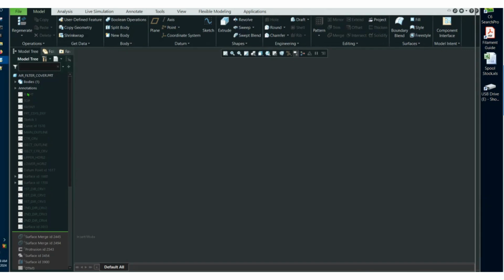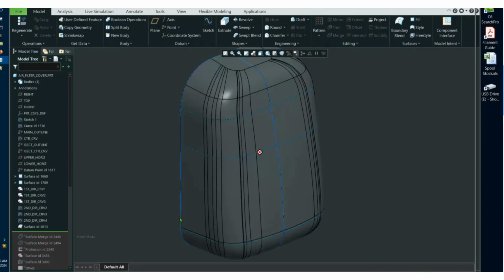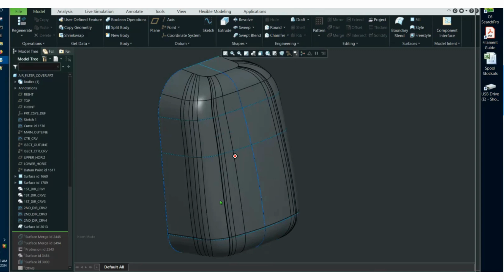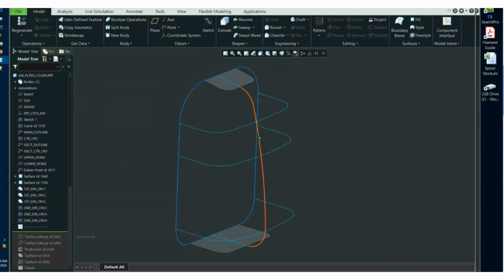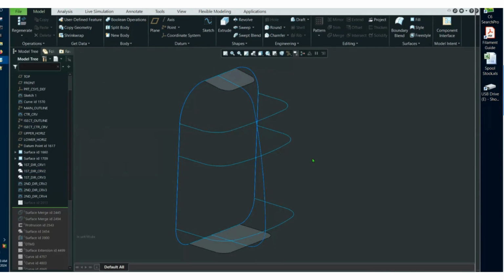The surface is quite horrifying. I mean, this looks terrible in terms of surface quality in this example. So one of the things is that when we make boundary blends and you don't utilize a key piece of functionality in it, you end up with stuff that looks like this, because all of the inputs have knots in them. These are separate pieces of sketch or whatever. So it can be really unfortunate. These don't have the same number of pieces. There's knots and things like that.